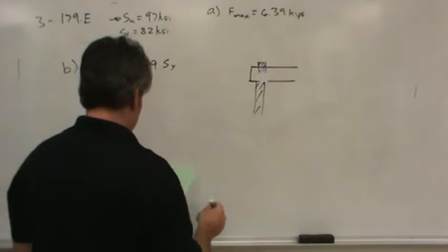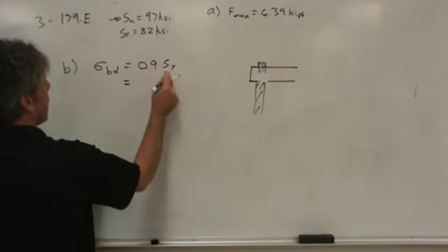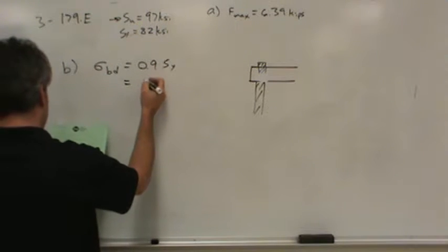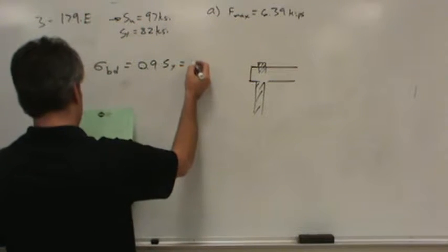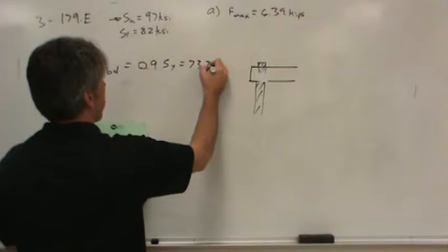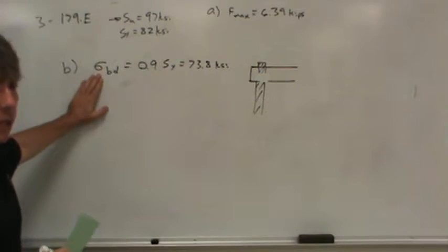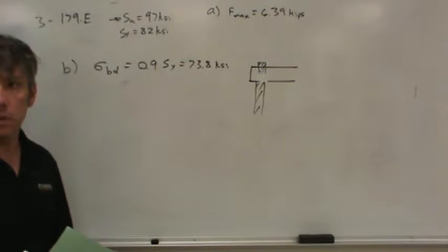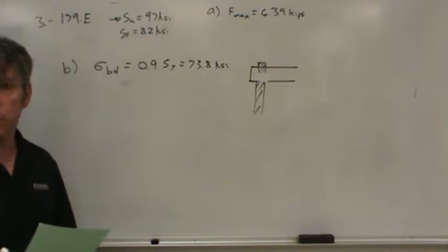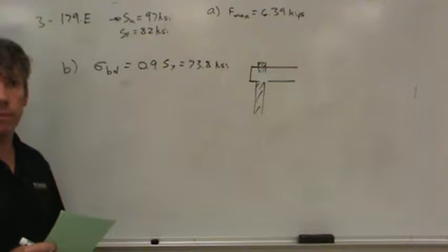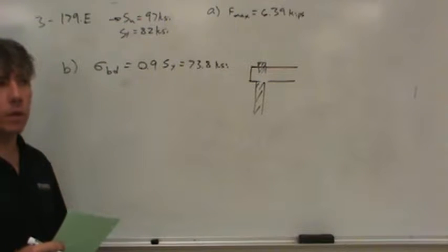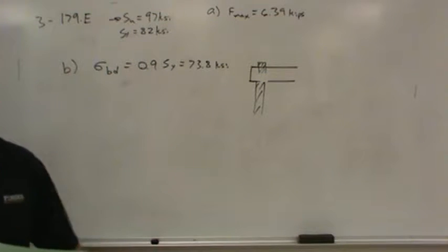Okay. All right, so continuing this, since the yield strength was 82 KSI, I'll just write it over here, we have the space. This comes out to 73.8 KSI. Now, why am I using a sigma here and I used a tau before? What's the difference between these two things? Why was the tau used? That little funny looking T thing.